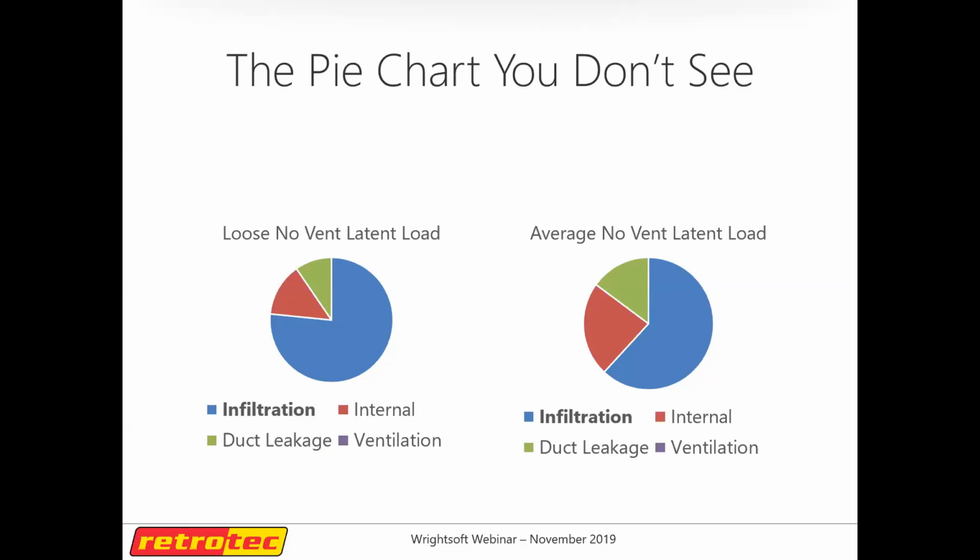And what you're going to notice is that in the winter months, the heating load is going to be a much more significant load than the cooling load, right? It has to do with the temperature differential. A hot day is 95 degrees. A cold day is 20 degrees. On the one hand, I've got a 75 degree temperature in the house and a 95 degree outdoors. That's a 20 degree delta T, or temperature difference. Versus on a cold day, you've got a 50 degree delta T, right? So in theory, I should have about 2.5 times as much load on the heating side as I do on the cooling side,